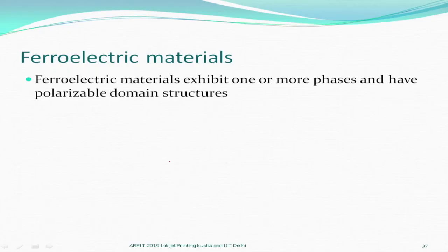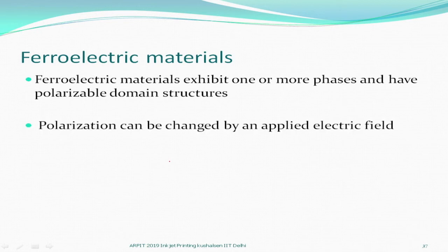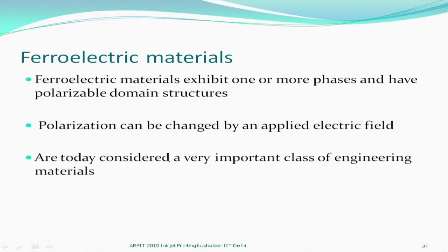So, you apply voltages, so polar entities could orient themselves in the direction of the applied voltage, and this polarization can be changed also by changing the applied electric field. This class of material, the ferroelectric piezoelectric material, is a very important class of engineering materials today.